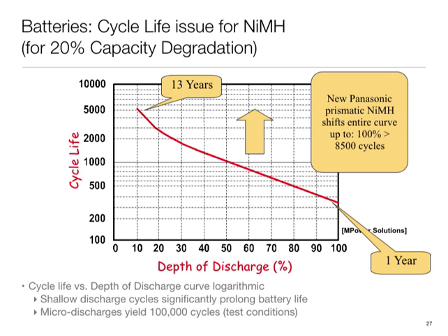In fact, if you do only micro charge discharge, then it could be hundreds of thousands of micro charge discharge. So the numbers that they're quoting really is near complete discharge and then backing it up. And I would emphasize that term near complete. If you let the battery deplete completely and not charge it pretty soon, or even let it stay there, then you're destroying the battery as well.